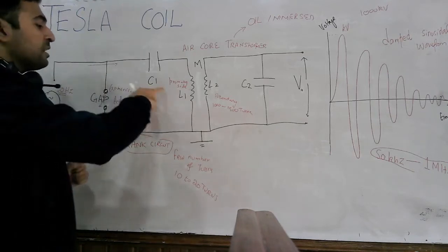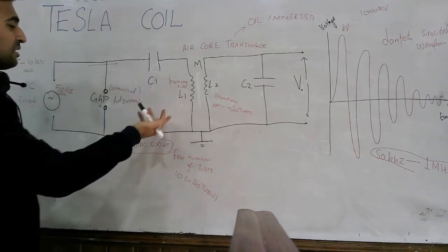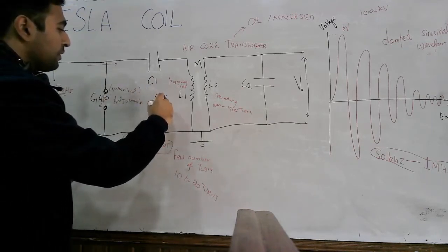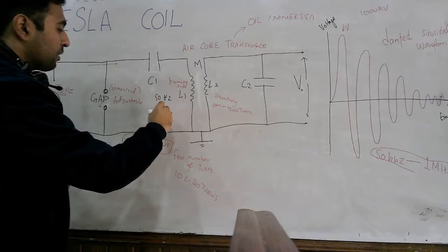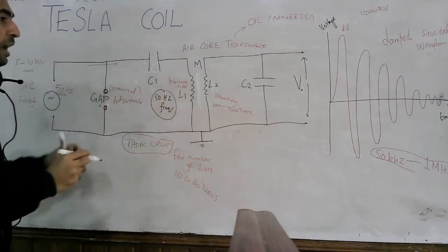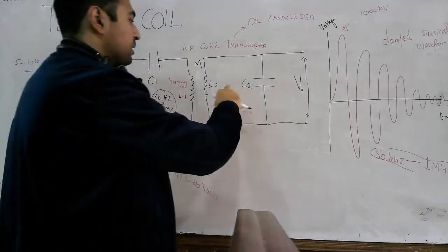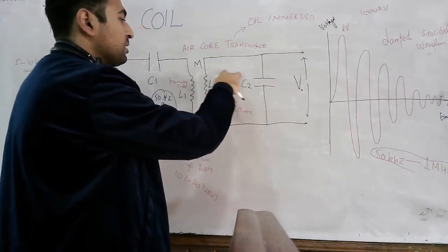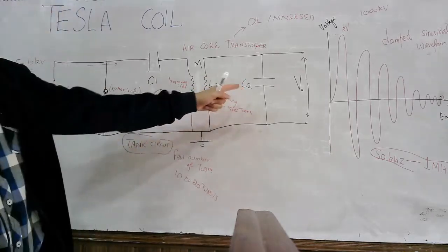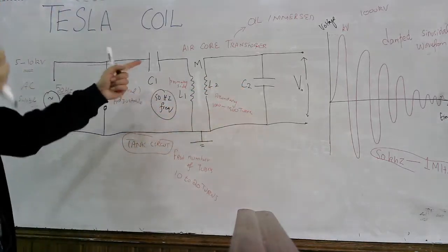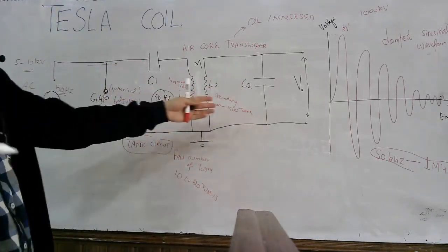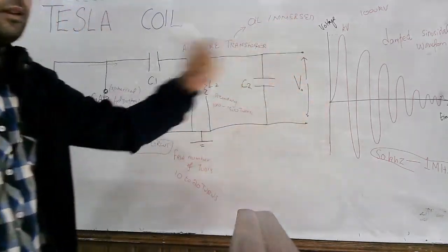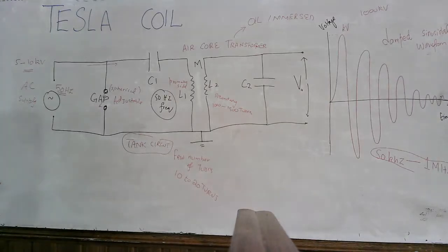The capacitor and inductor values are chosen such that they resonate at the 50 Hertz frequency, and this inductor and capacitor are chosen such that their resonant frequency also matches here. And what happens next? You will see the development of the high voltage, high frequency waveform.